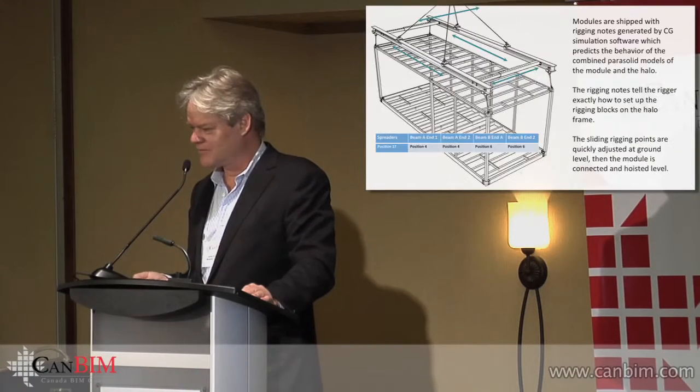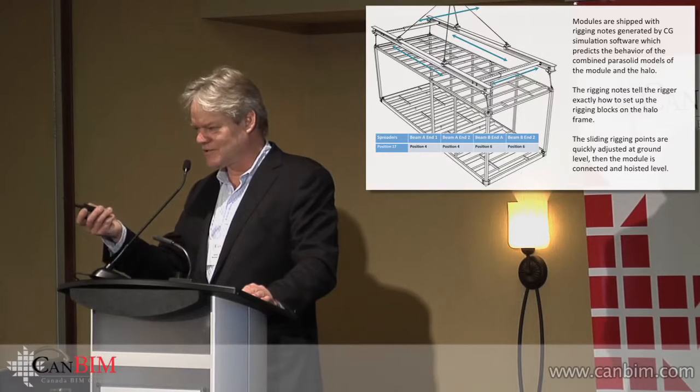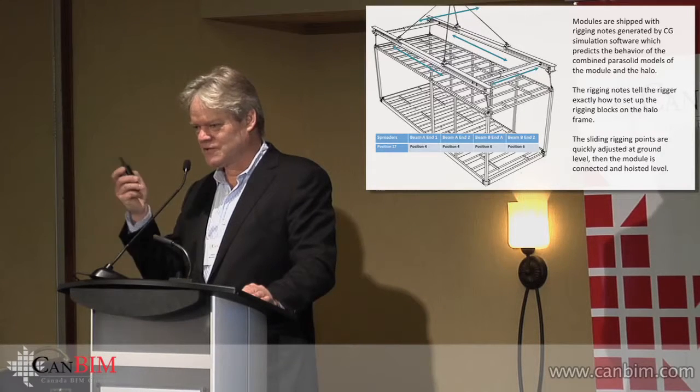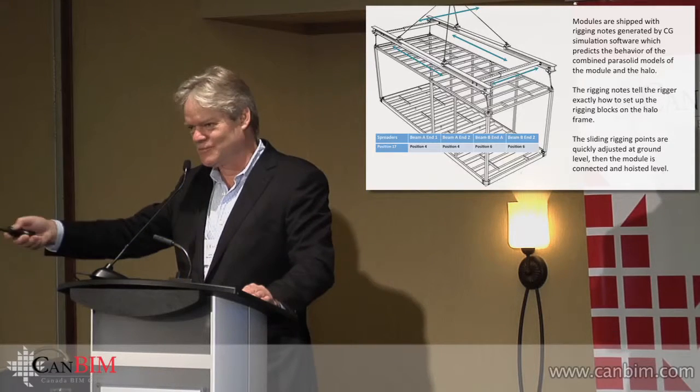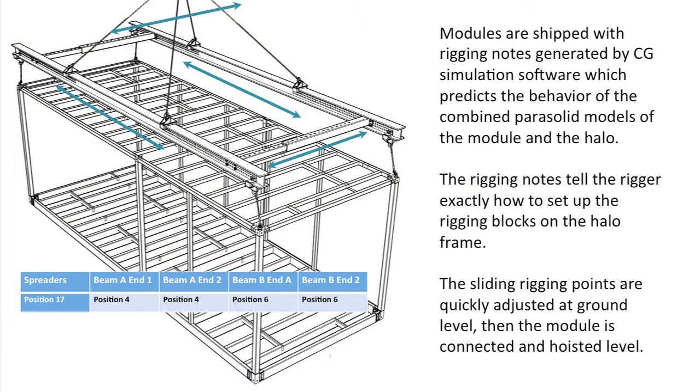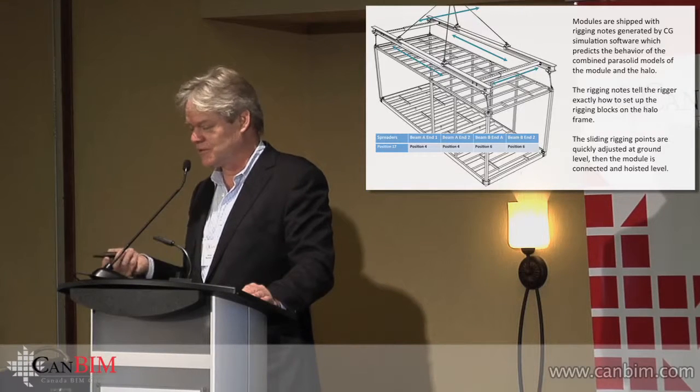accurate anchor point so that, as you see here, the halo frame, if you've designed these things in a single source of truth parasolid modeling platform, and you know the weight of every stud and every screw and every sheet of wallboard and every pipe, you can set up this halo in accordance with the center of gravity data, and this thing will pick and fly level out of the box. And that's exactly what we were able to achieve, by the way, on the bow.